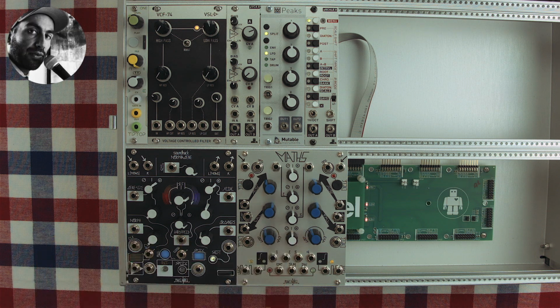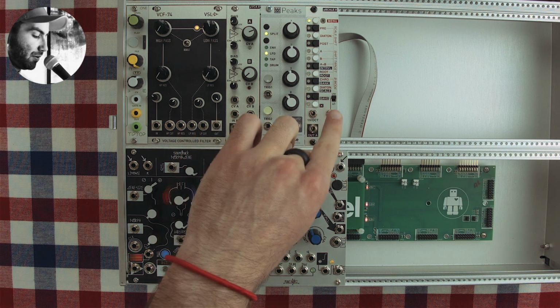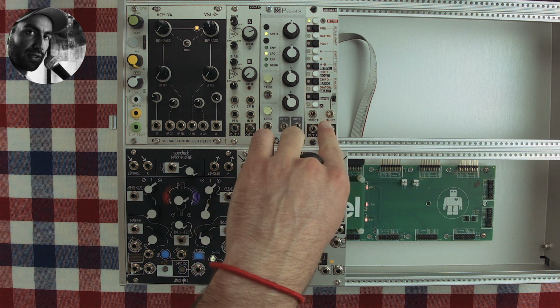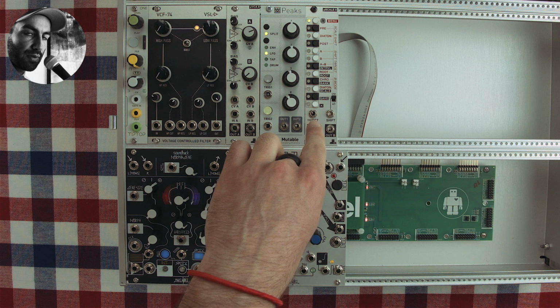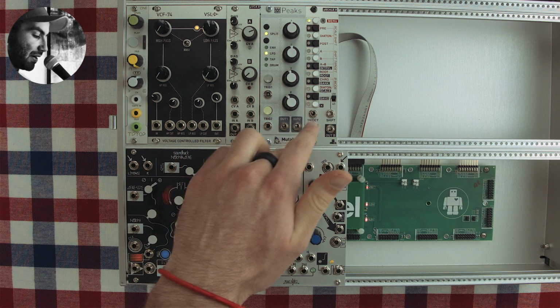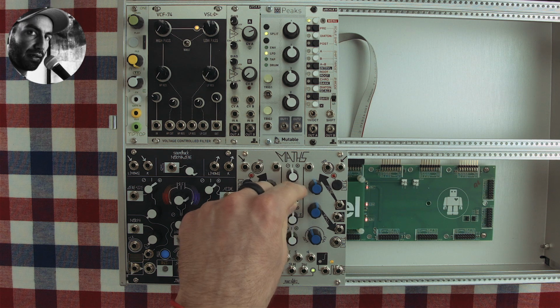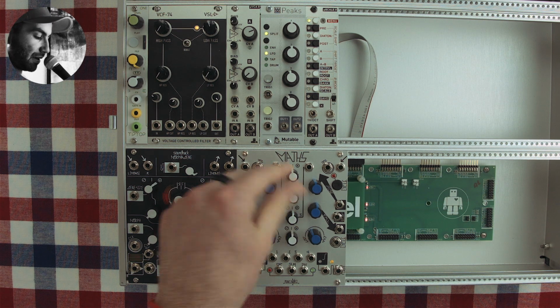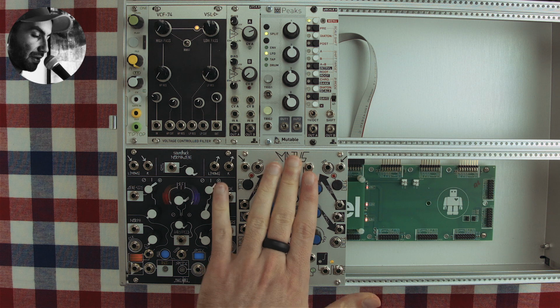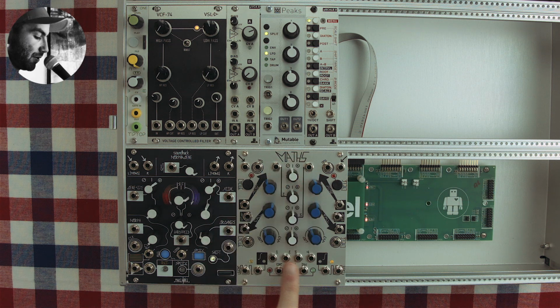So if you remember the sum equation, AX1 plus BX2 plus CX3 plus DX4, if you don't patch anything into channel 2 and 3, the X2 and X3 values effectively get set to 10 and 5 respectively. So you effectively get constants to play with. And then you can still attenuate and multiply plus or minus how much of that offset you want to put into your equation.